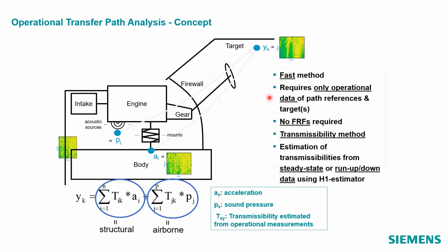And as we show an example here, I would have a microphone in the car. On the passive side of my mounts, I would have accelerometers. I would calculate the transmissibility, microphone divided by the accelerometer, multiply it by the same acceleration to predict that contribution. And we would do that for the airborne, and we would also do that for the structure-borne.